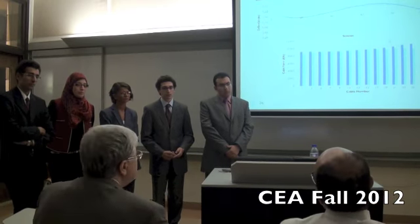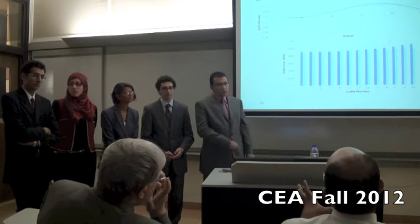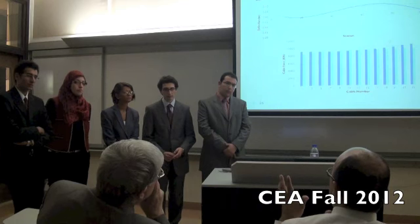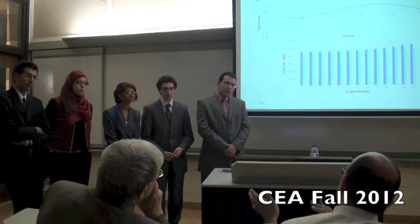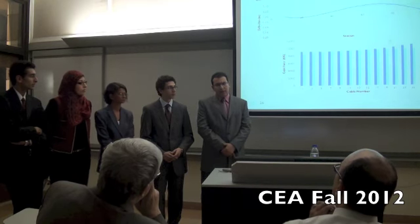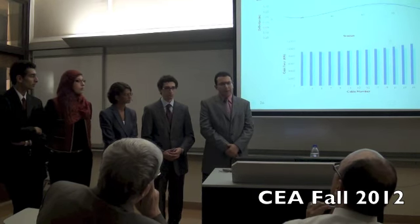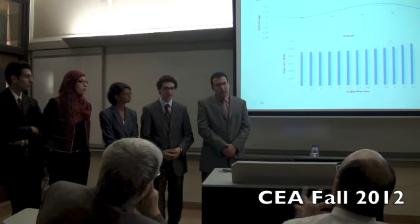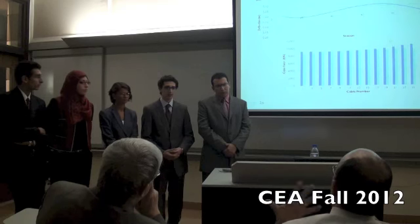Runtime. You mentioned that you are always using a reduced model. I wanted to know the runtime for the reduced model. How long does it take? For the dead load only, it takes like 3 minutes. However, for the dead load and the moving loads, it takes like 10 minutes, half an hour.